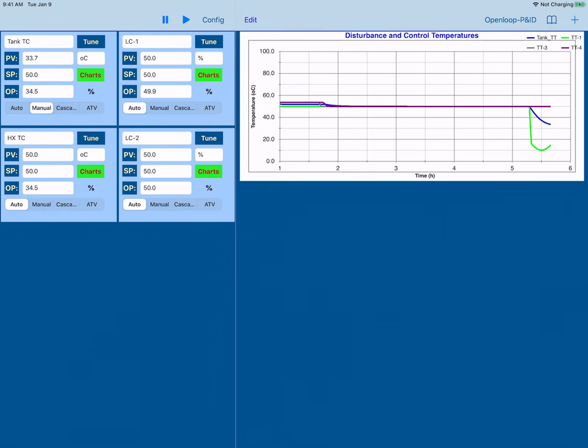The green curve is the disturbance stream, and it's going to show plus minus 40 degrees as we set it. But remember, when it blends with the heated stream, it's going to result in plus minus 20 degrees. So that's the maximum that the tank can attain. The blue curve is the tank temperature, and you can already see in the simulation here that the green curve reaches the zero line there, and the blue curve lags and comes up there and crosses the line. So we have definitely a little bit of lag between the two curves.